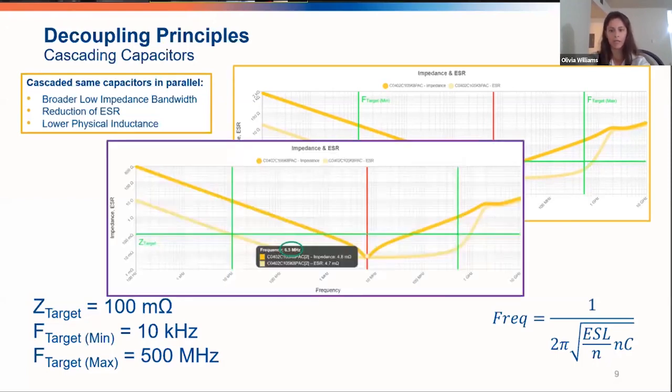There we have it. And we can see that the self-resonant frequency, or series resonance frequency, doesn't change at all when we add them in parallel. And the impedance does come down a little bit, closer at our target frequencies, but still we're too far off. So we've got 2 in parallel there.